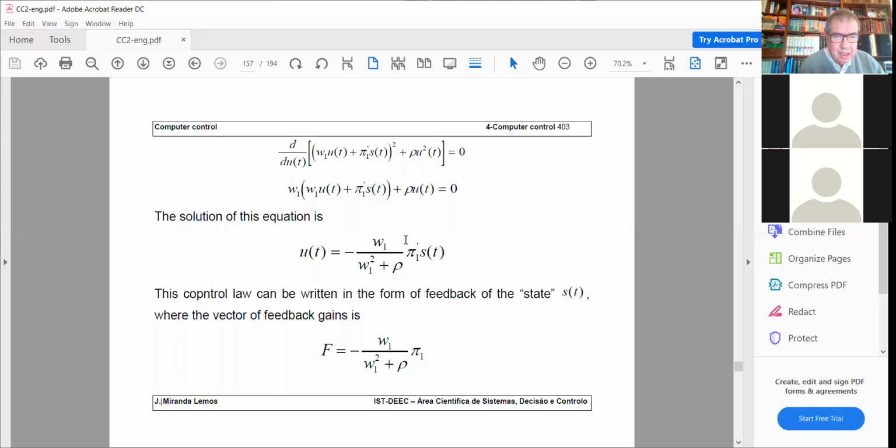That's exactly minimum variance control. When rho increases, you are changing the gains, and you are changing the position of the poles, and so we call this detuned minimum variance. So one approach, by playing with this rho, you can stabilize non-minimum phase plants.